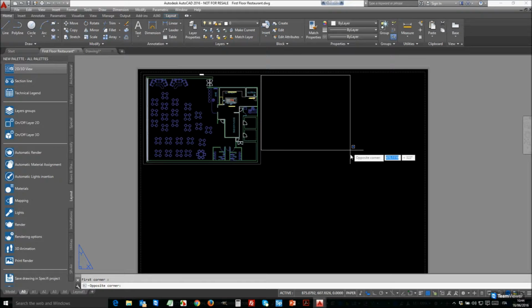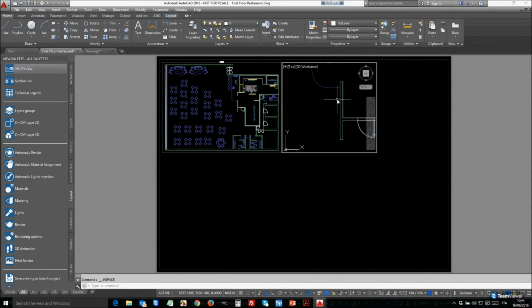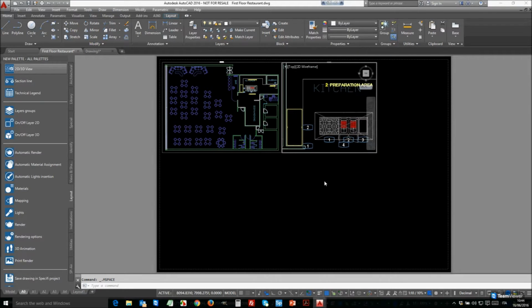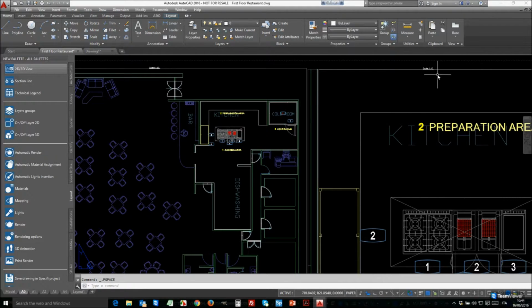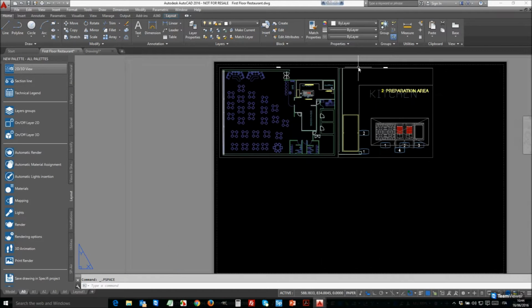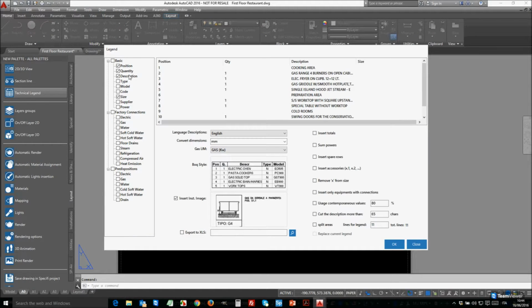I can call the command again to add other viewports, supposing I want another plan with a different scale factor because I want to detail my cooking island. I can also remove auto size and lock view, these two options, because I want to identify exactly by myself the area where it has to insert the viewport. So I can identify the 2 corners. I can enter inside, and with the AutoCAD pan command, I can center. So we have the same project, only one project, but with different viewports. It's similar to inserting a camera and taking some picture, some photo directly from our project.